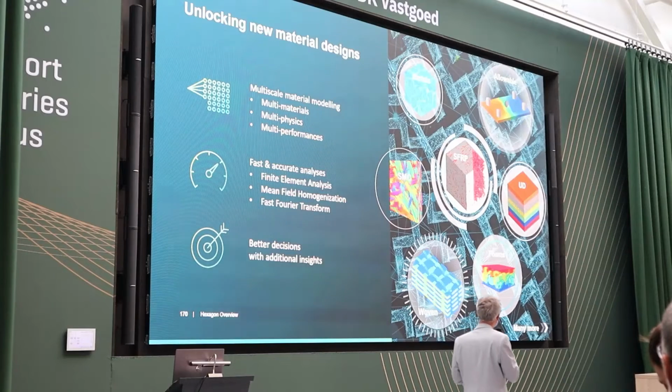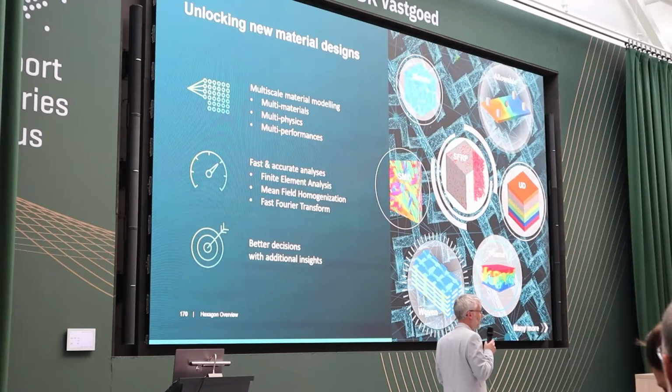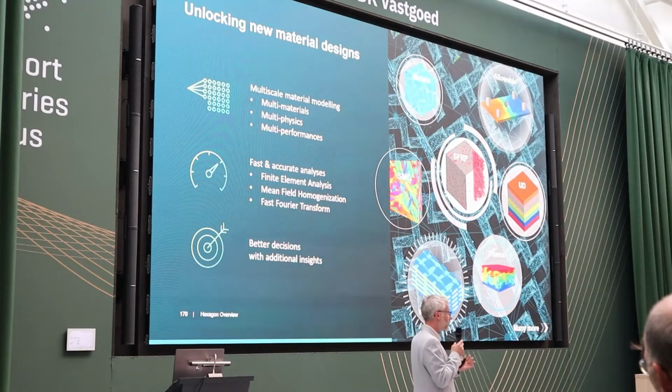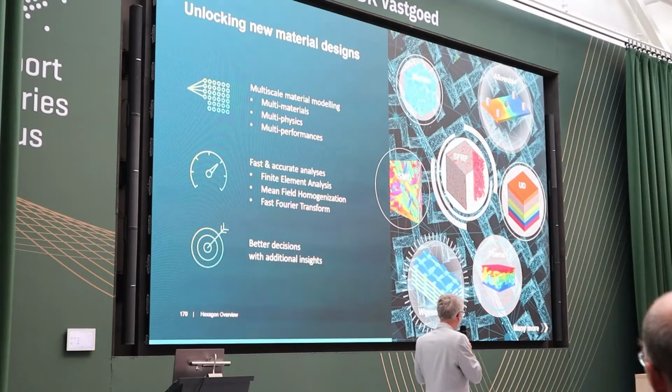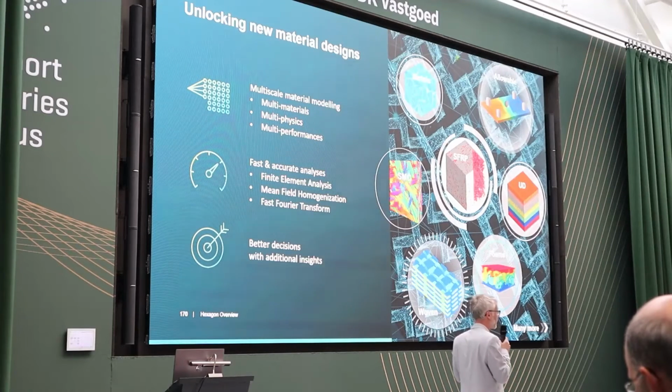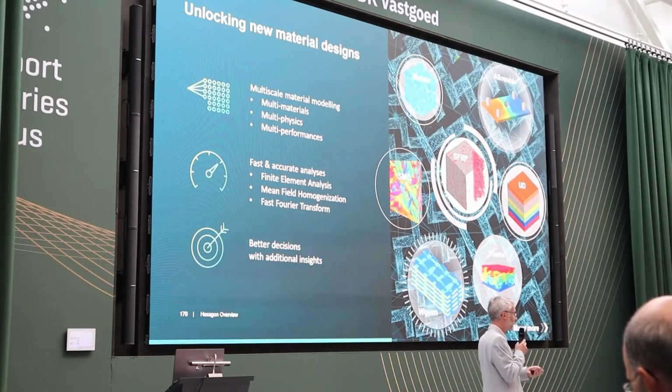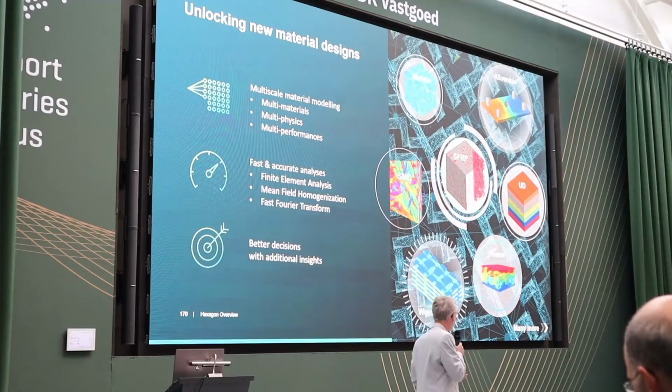And we are not going to have one unique tool to predict the behavior of the material. We are going to work between finite element solutions and mean field homogenization solutions, in order to offer you the right tools for the predictions or the study that you would like to do, to better understand your material and be able to take the right decisions on your material design.